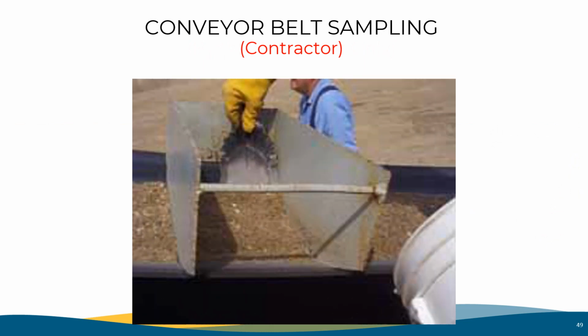The first method is conveyor belt sampling. They must stop the plant in order to obtain the sample. A template is used to block out a section of material on the conveyor belt. Then the material is scooped out. All material within the template needs to be removed. The fine material will be swept out with a brush and collected. This will need to be repeated to get 3 increment samples.